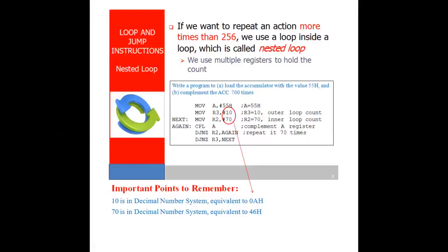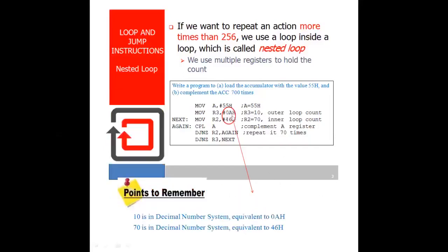Okay, so my suggestion is that you should write with the hex number, as we have already considered here the 55x. Then you have to write here XX, because we are using pen and paper, but actually it is the software directives. Where we write without the symbol H or D, it will be treated as D, meaning decimal number. Okay, but it is the software directives maintained. So we shall consider it as 0A hex, which is the decimal equivalent to 10.